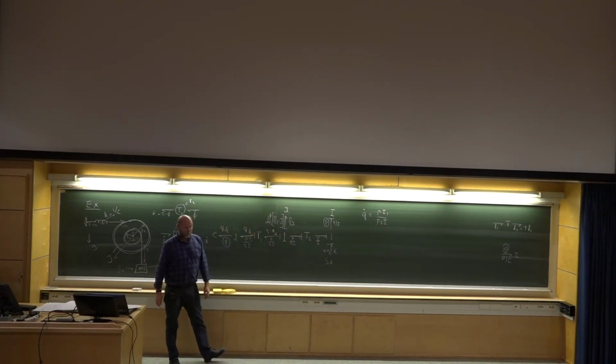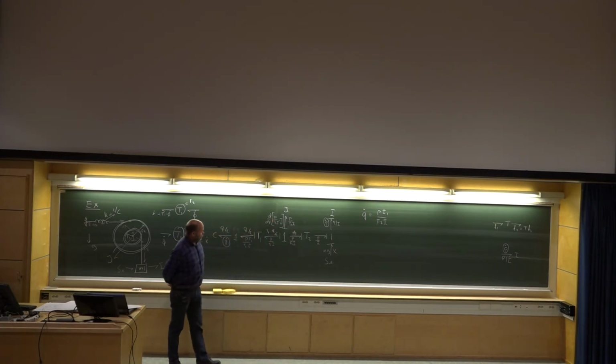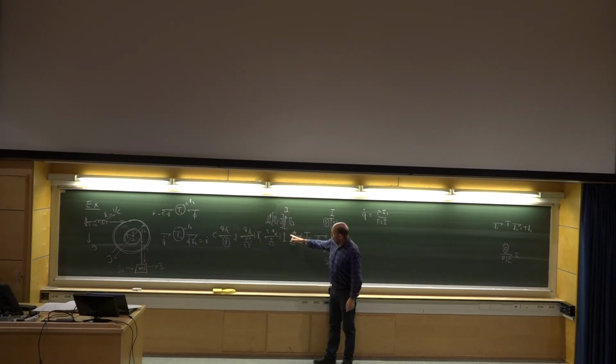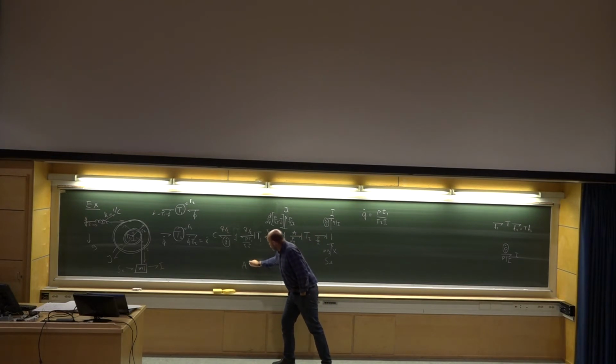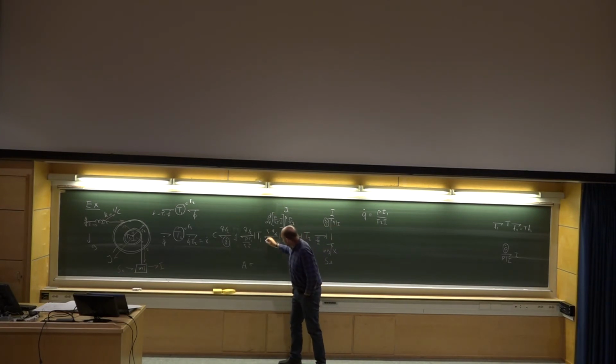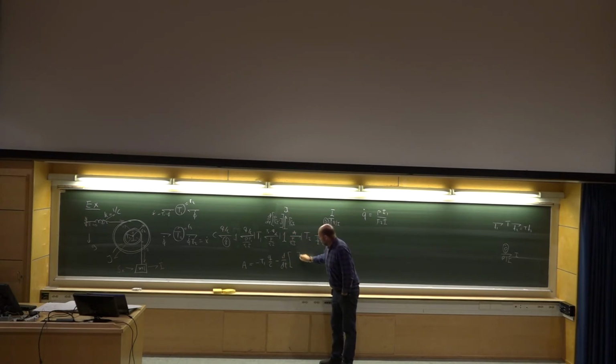And now you see I'm running out of space. So let's invent a variable A here. What will this A variable be? What's this effort here? Well, here I now have to use the summation rule around this one junction. I'm finding the effort that goes out from the one junction equals what comes in, and nothing comes in, everything goes out. Hence this A has to be equal to minus T1 Q over C minus, and then this time derivative of this bracket.